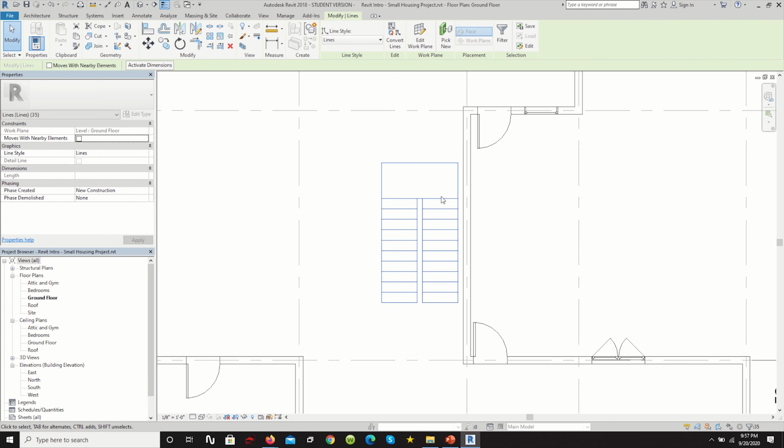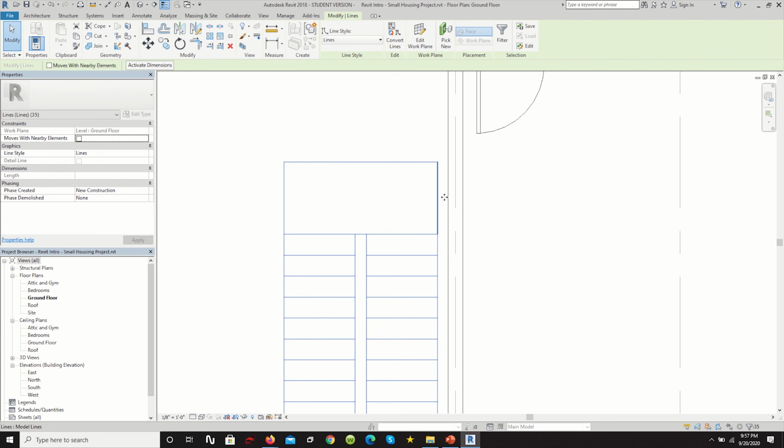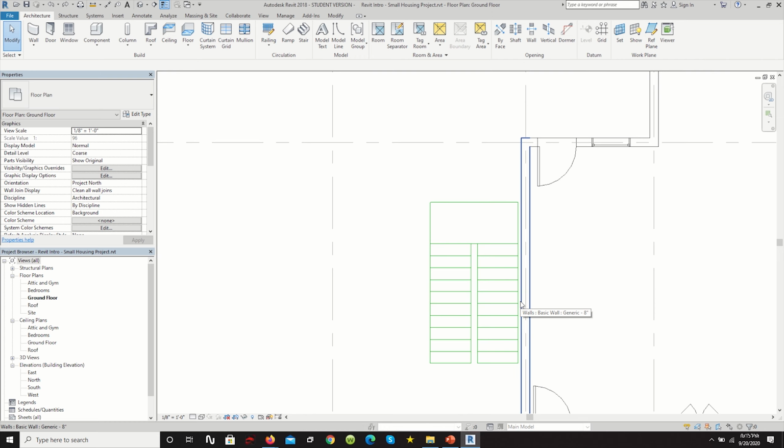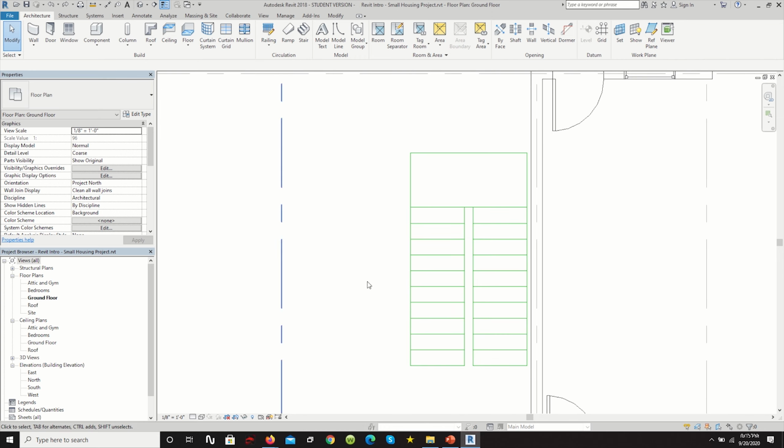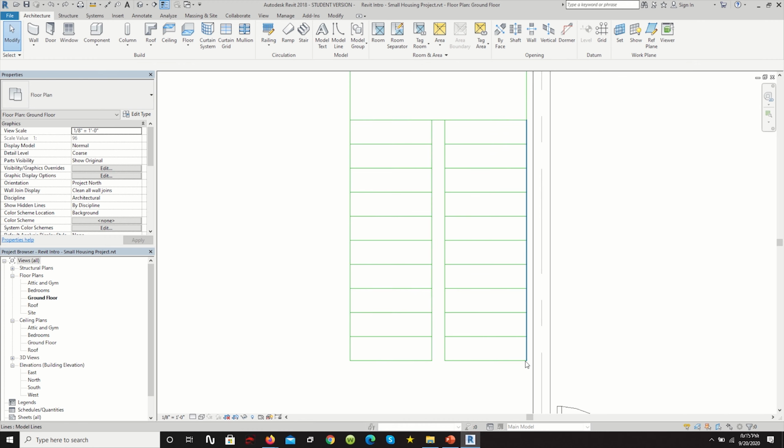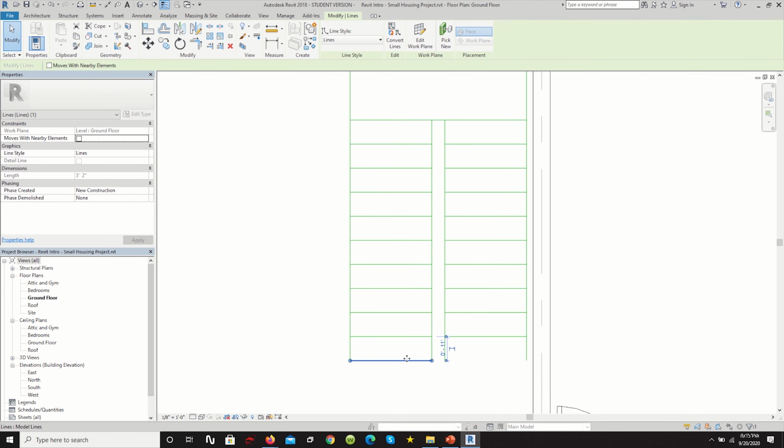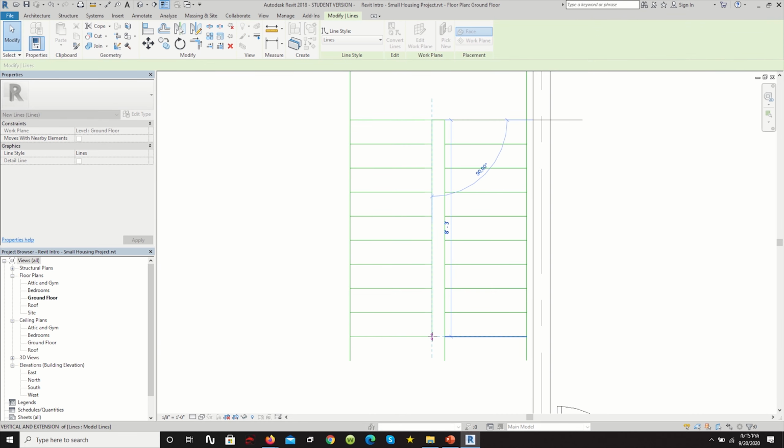So let's select this. We can just move it a little closer to the wall if we want to, or technically we want to have it against the wall. So now we've made our sketch for our staircase, and we want to just make a quick adjustment because we calculated this to be 6-inch risers, but then we have 2 extra treads here, so there should only be 10 treads on each side. So that's a slight mistake. Let's delete that quickly. Let's move this up, move that up.